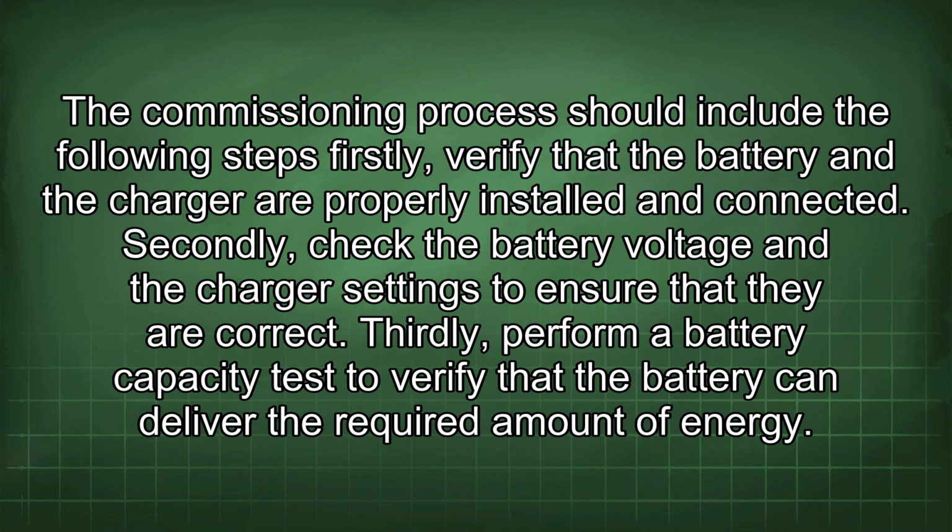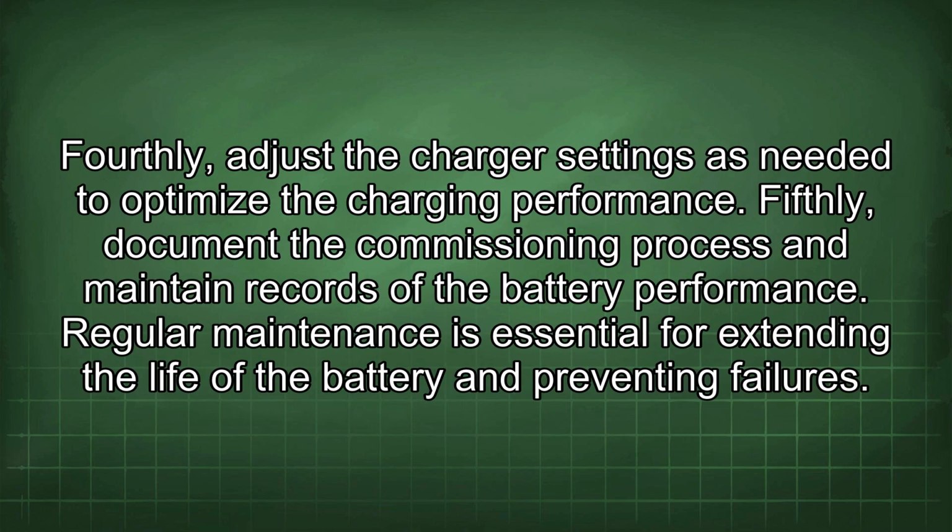Thirdly, perform a battery capacity test to verify that the battery can deliver the required amount of energy. Fourthly, adjust the charger settings as needed to optimize the charging performance. Fifthly, document the commissioning process and maintain records of the battery performance.